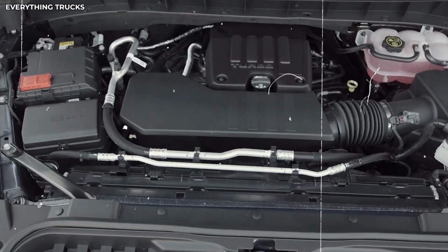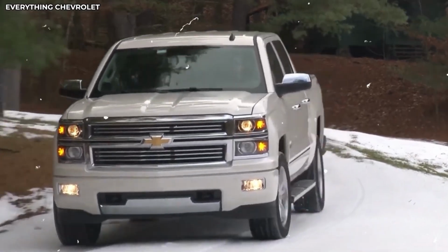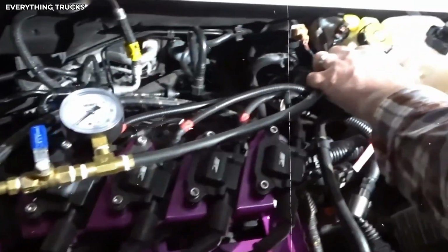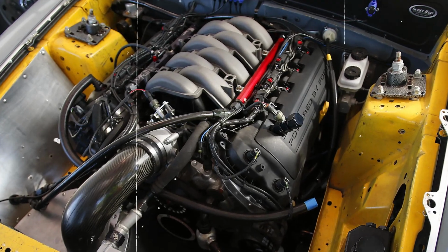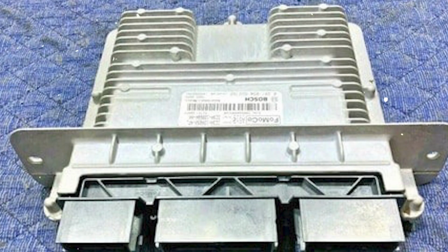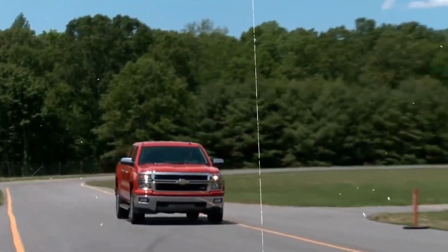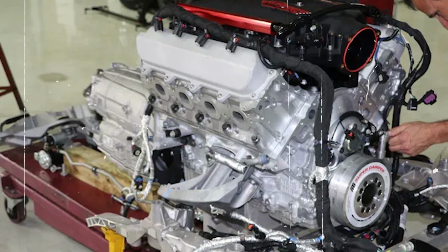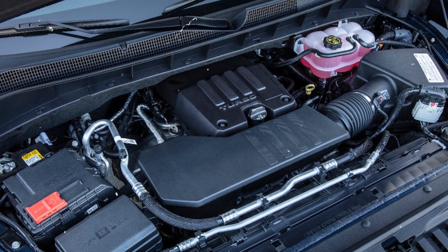For example, on 2015 to 2020 F-150s with EcoBoost engines, there's a specific hex code that controls throttle aggression on a scale from 1 to 10. Factory default is usually 5 or 6. Changing it to 8 or 9 delivers sport mode-like throttle response in normal driving mode. After making your changes, write the modified data back to the PCM. ForScan will warn you that modifying as-built data can cause problems. Acknowledge the warning and proceed.